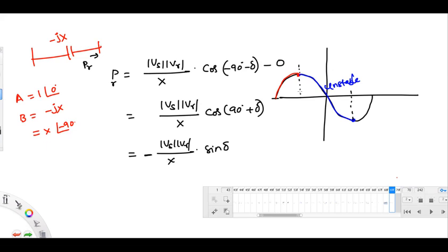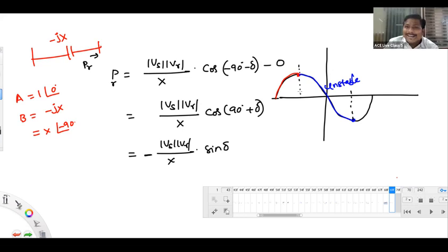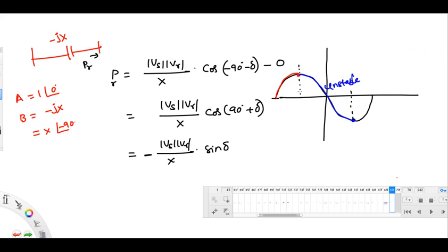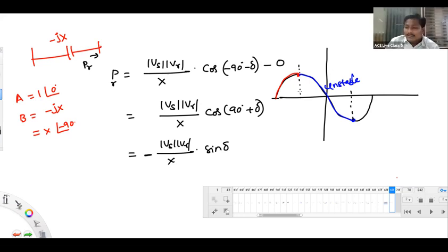But sir, the same concept means for delta increment, delta is in our control now. Who said delta is in our control? Delta will be controlled by load. According to load variation, delta will be commanded. Or you can say not only load, this transfer reactance is also one of the factors.